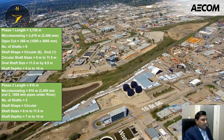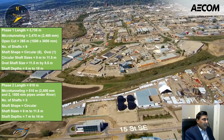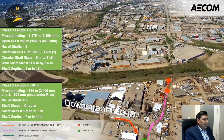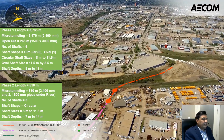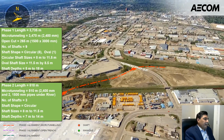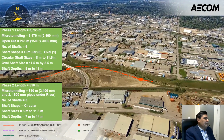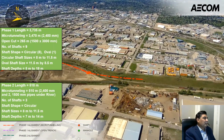Starting from Bonnybrook wastewater treatment plant, the first section is open cut and followed by microtunneling. So the microtunneling length was approximately 3.4 kilometers, and on the video you can see purple line is the open cut section. Red line is phase 1 microtunneling. Red circles are shafts which are used to launch and retrieve microtunneling boring machines. So microtunneling section for phase 1 was about 3.4 kilometers long and open cut was 265 meters long. Microtunneling size was 2400 millimeter and open cut was 1500 by 3000 millimeter box culvert.